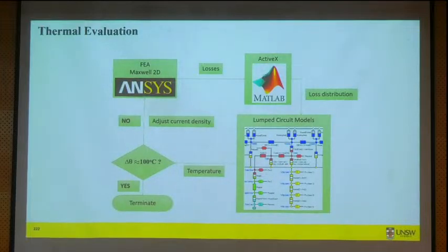So thermal can be done through some lumped circuit model, or ANSYS has a thermal test bench. Thermal test bench can be used as well. So if we do it outside, then the losses go to MATLAB, and then MATLAB can input to the thermal circuit model. Okay? And that gives you the temperature, and then you check whether it is within your temperature limit or not.